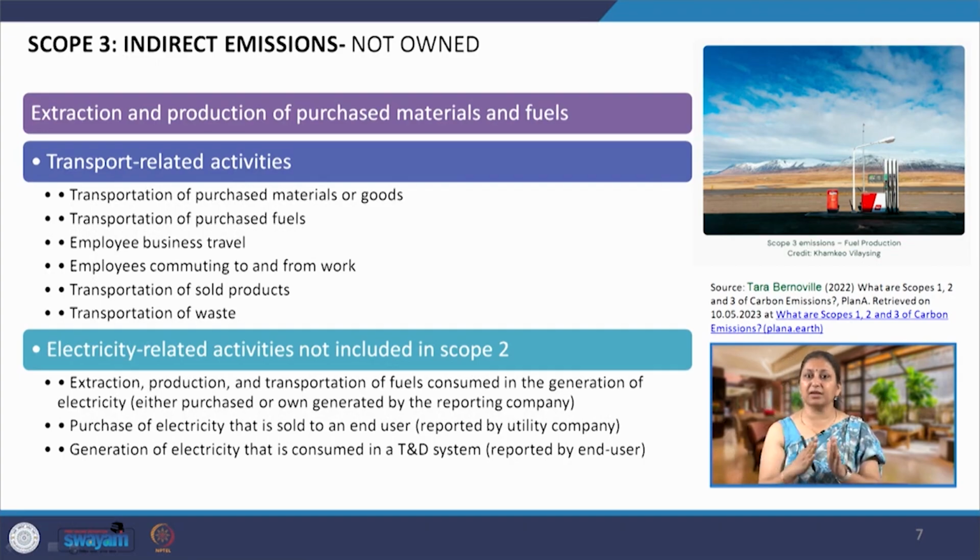So, if we compare the emissions of these two blocks, none of this is going to be manufactured on my site. They might be giving me similar thermal performance, so that my operational energy is the same, but the embodied energy associated with these two different products will give me the scope 3 emissions that my company will also be declaring. So, the choice of material, the entire value chain and the choices that I have through my entire value chain, will determine these indirect emissions.